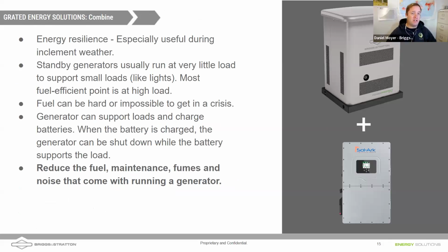Nathan, we have a slew of questions, and I really like this because this is going to open up the conversation to where we're interested. Conrad's asking, what size generator is possible on the Solarc 15K? You mentioned it a little bit, 80 amps continuous on that gen port. That's 19.2 kilowatts. What about on the grid port, though?